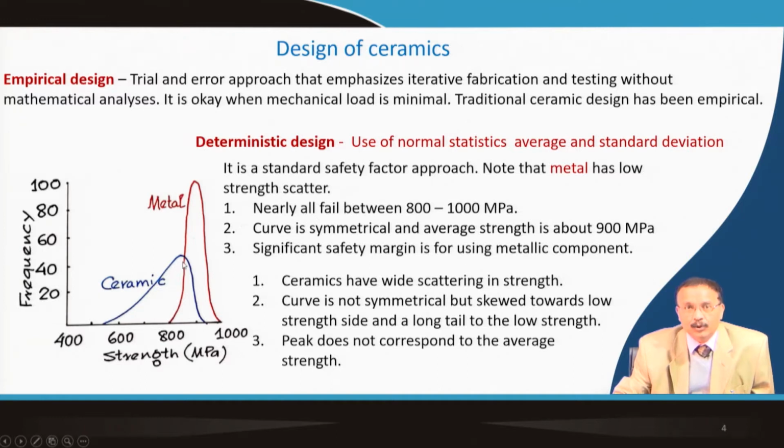Right. So, here it is very difficult for you to identify the design stress. The design stress will be much less if you have a skewed kind of pattern, and this also has a long tail. So, it can extend further, 200, 300 something like that. So, for practical application this is a real problem to use any of the sintered ceramic material.